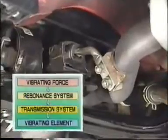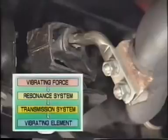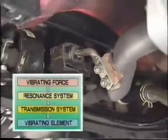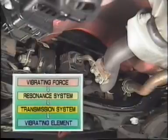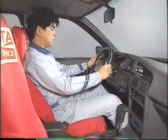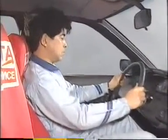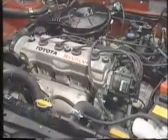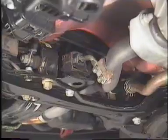The exhaust pipe support forms a vibration transmission system, and the body is the vibrating element. The vibrating element causes the air to vibrate, and the vibration of the air is transmitted to the driver's ears as the booming. Sorting out the various elements of a problem is very important for troubleshooting, and you should always analyze problems in this way.